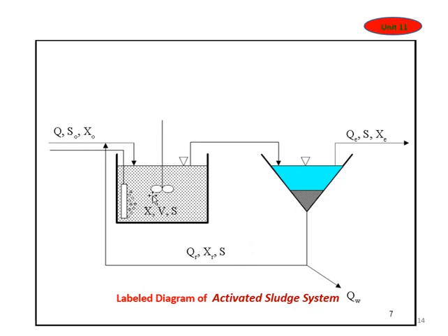The activated sludge system consists of an aeration tank and a sedimentation tank. This is the complete activated sludge system. So there is some wastewater coming, having some bacteria, some food, and in this we provide mixing with a fan, or maybe injecting air by some diffuser. So there will be more oxygen, the bacteria will be there, and the waste material there.